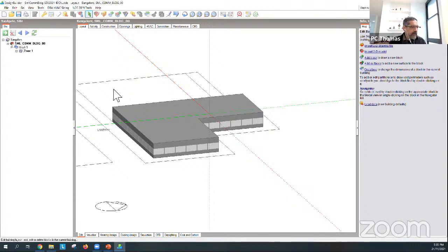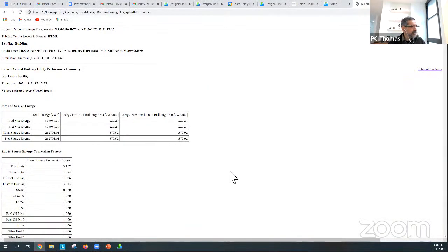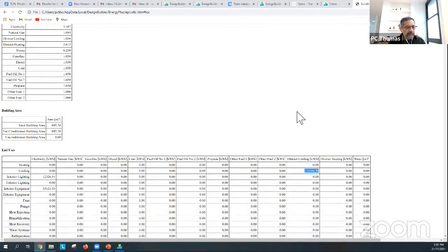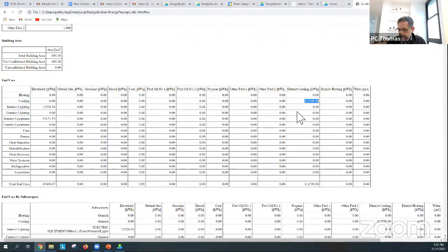Okay. So I'm going to change the solar heat gain coefficient, and I'm going to lower that so less of the solar radiation comes in. And what we'll do is we'll just keep in mind what is this number. So I'm going to write that down. You guys might want to as well. So it's 112,590 kilowatt hours. And as I said, this is thermal energy, not electrical. If you divide by 2.5, the COP, then that's a rough indication of what the electricity usage would be.